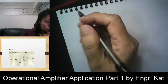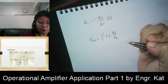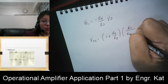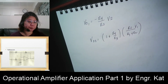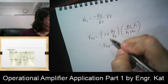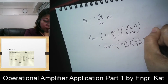For VO2, so let us call that VO2, that is a non-inverting amplifier. So we have 1 plus R4 all over R3, multiplied by the input voltage. But what is the input voltage? The input voltage is the voltage across R2. So we have a voltage divider between R1 and R2 multiplied by our V1 here. To get the total output voltage, that is a combination of 1 plus R4 all over R3 multiplied by R2 all over R1 plus R2 multiplied by V1.